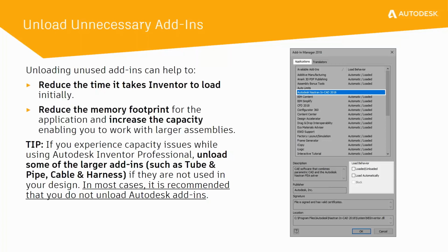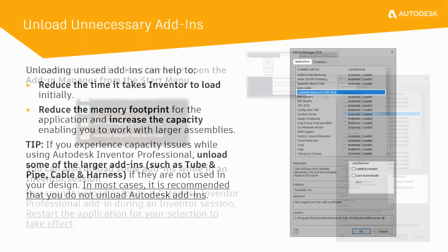Now, the reality is this is going to reduce the time that it takes for Inventor to load and reduce the memory footprint, but we don't want to recommend that everyone does this. This is not a solution to anything other than to help you with large assembly performance if you're already suffering. Our recommendation is that you don't unload these Autodesk add-ins and that you do retain the automatic loading of those unless you're getting large performance issues.